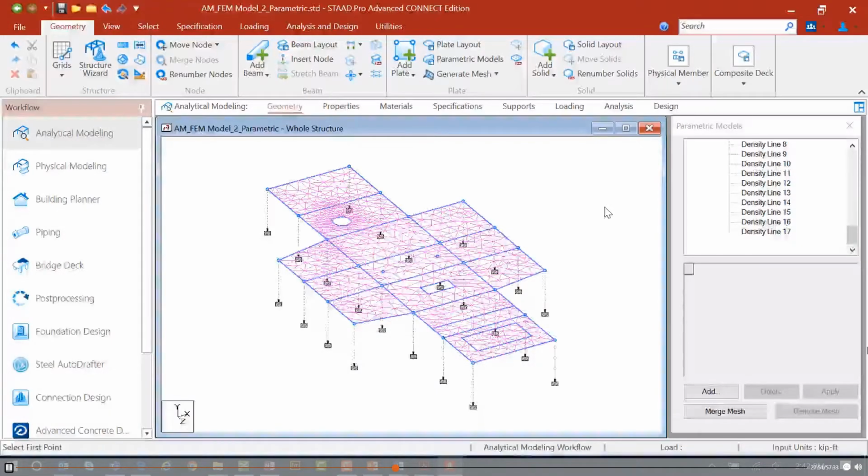Your second major advantage is recognizing interior nodes. So during the process of meshing, the program will automatically take into consideration existing nodes that lie within the boundary of the panel, but are not chosen as corner nodes of the panel. You can simply define the panel boundary, like we did here. So the remainder of the nodes will be automatically considered by the program as control points, which is to say that elements will be created in such a manner that some of those elements will have these nodes in their incidence list.